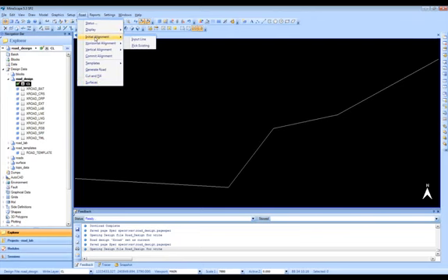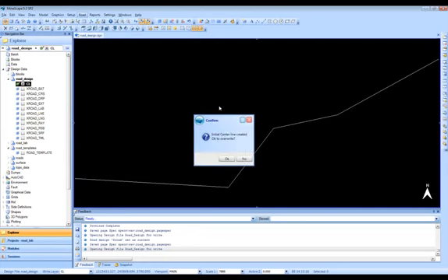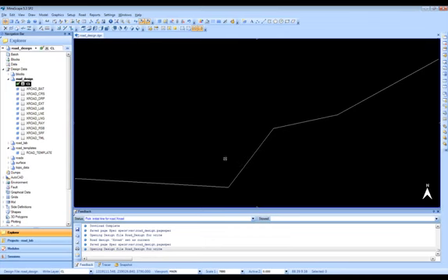So this is pretty much laid out in the way that you're going to create this design file, this road. So under initial alignment, you need to say, what is the center line of your road? You can input a line, which means if you select that, you're just going to be asked to enter the points. I happen to have one already on screen, so I'm just going to pick existing, and it's going to give me a message, okay, override, yes, and I'm going to select this line. And that line will now become my road center line.